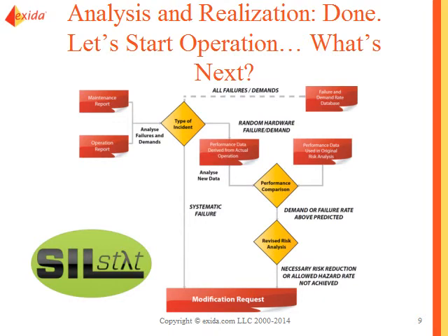Now, if the numbers line up exactly, then you would be spot on. If you come to the conclusion that your demands occur, let's say, once every 5 years, and you assumed once every 50 years, then you're an order of magnitude off in the wrong direction. Your process is apparently more hazardous, higher risk than you originally expected.